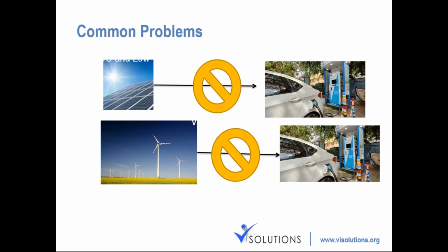So this is going to be pure DC of different levels, and the voltage level of your renewable energy source, the solar panel, and the battery in your traction vehicle, that is the electrical vehicle, is going to require a little different voltage. And if you take your wind turbine as a source, it's going to produce variable frequency AC, depending on the speed of rotation. And in order to convert that to something which can charge your battery, we need, of course, again a power converter.